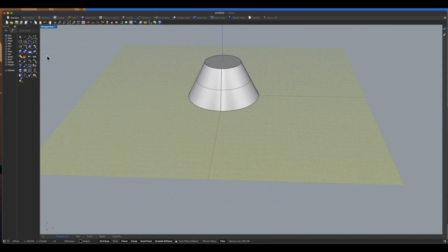Now we will create the other cone. Same box section. In that, take cone, left click. Now the point is 0 comma 0 comma 50, z height 50. Circle has been made. Now I will keep it 20, you can keep it as 20 mm. Then you can keep the height as 100 mm.